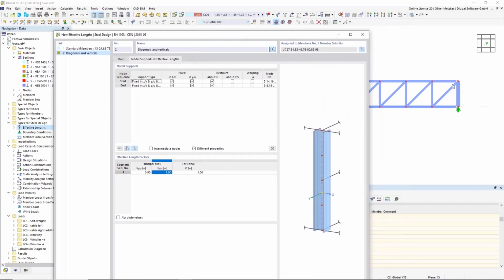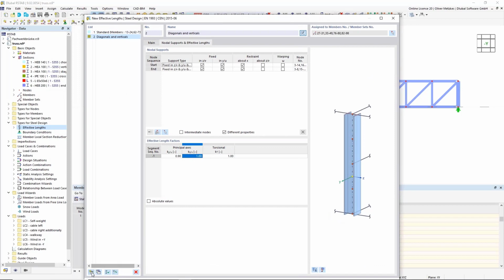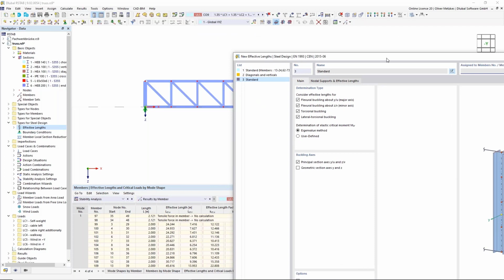Okay. For these frame members, we could also set this effective length, but it would be a bit more complicated for the buckling in the plane of the frame, because the frames could also have buckling factors, for example, of 3 or 4, and we don't have this lateral restraint at the top because, well, basically this frame is the lateral restraint of the whole structure. So I would not set a lateral support here at the top. But we could also calculate this effective length factor by using stability analysis. If we would do so, we would find critical load factors around 40, for example.